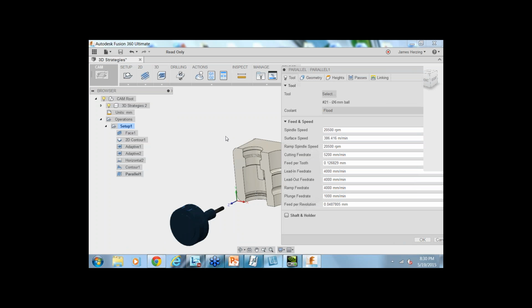This and the next three are pretty much all for finishing and detail work. So this one, the parallel, and then using pencil are all for the finer details and milling away smaller amounts of material. I think you'll see in the next few steps, we're probably changing the tool too often because we're using three different sizes each step, even though it's doing the same thing over and over again.